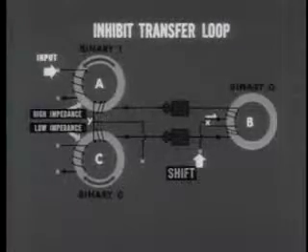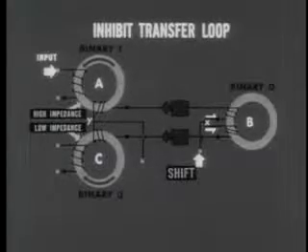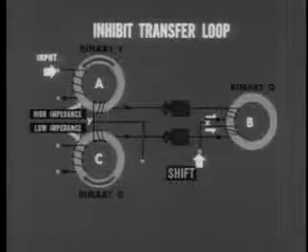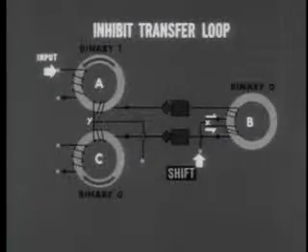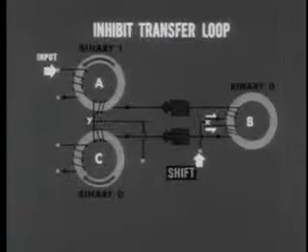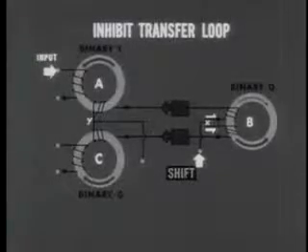The upper branch, which comes up against the high impedance at core A, is small. The lower branch, which has only the low impedance at core C to overcome, is large. The result at core B is the same as it was with the split winding loop, a weak negative flux and a strong positive flux, and therefore B is switched to the binary 1 state.